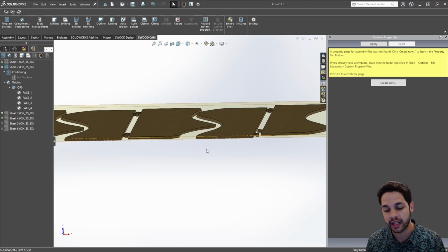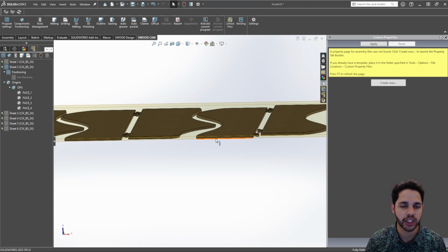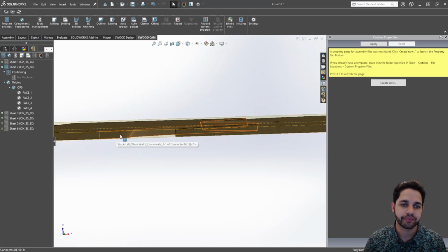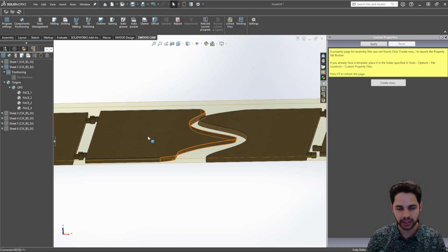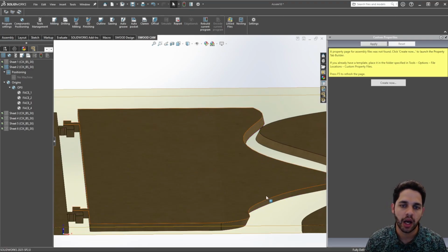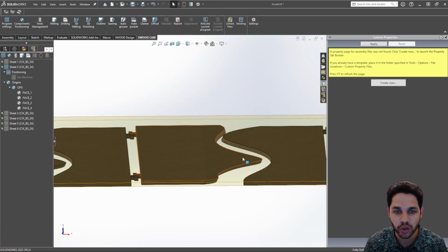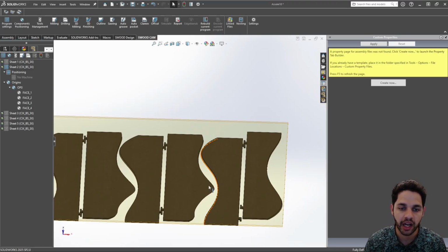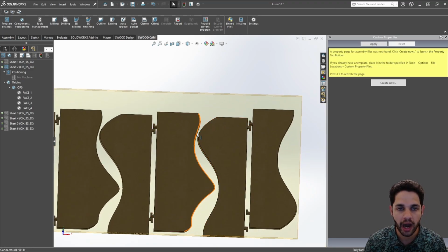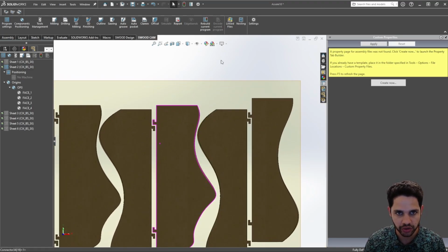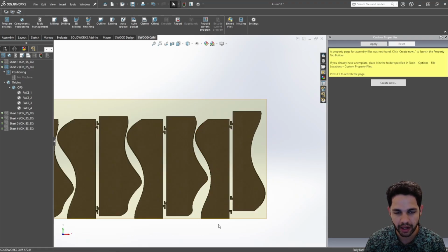I have actually only, the only CNC machine that I've had access to personally, I have done some programming on a pod and rail machine, but the one that I've actually been able to operate has been a nesting machine. So for this, I'd probably just do a contouring toolpath, and it's just going to cut these panels squared off as they are. So as you see them here, it'll just come out and cut that, whatever's sticking out the furthest, it would keep that contour profile.